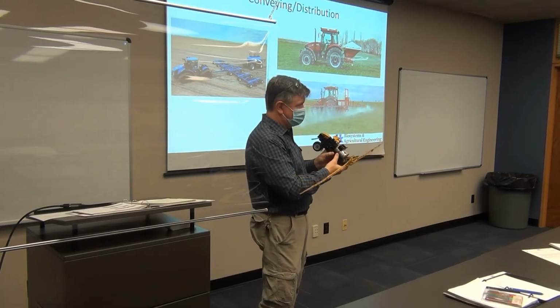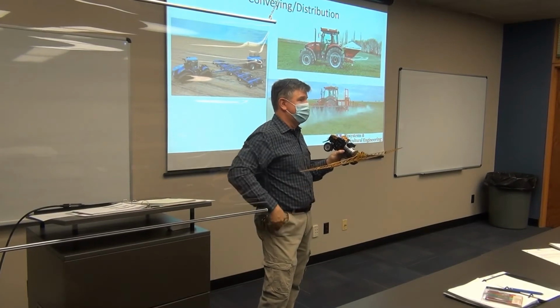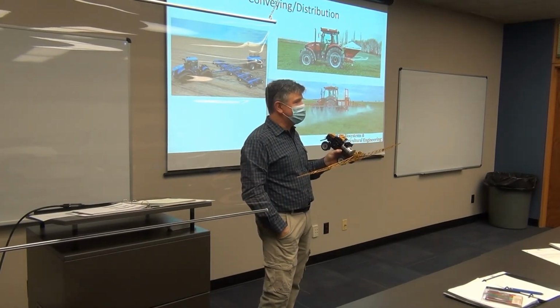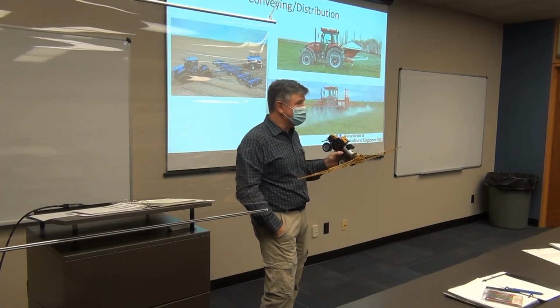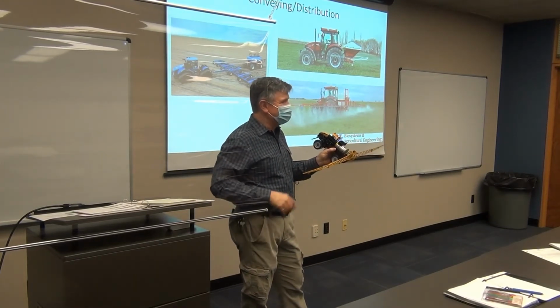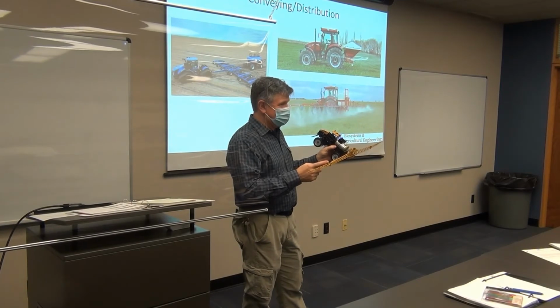This may not make sense, but would they design everything based on the nozzle that's furthest away and then just keep uniformity going inward? So how would you do that? The answer is yes. Determine, I don't know, the flow rate that you actually want, then find the pressure out there, and then whatever pressure, you determine your nozzle size, and then you just keep it the same on the inner ones, maybe?